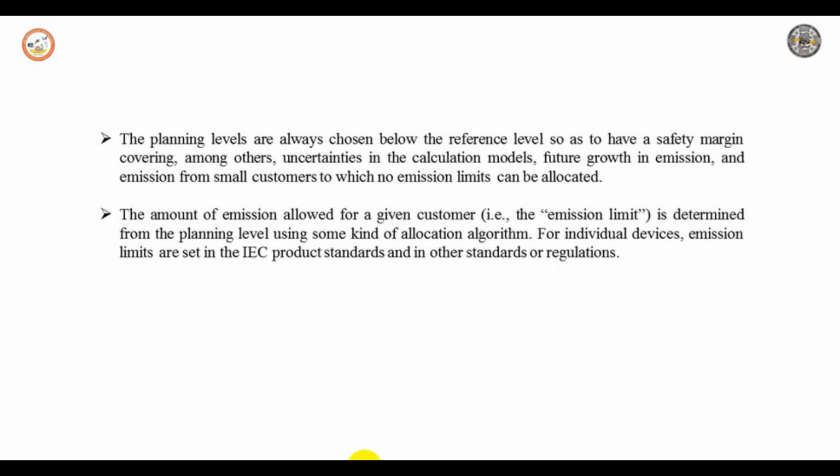The next step to consider is related to an increase in the reference level. This is more difficult because it probably requires changes in international standards on electromagnetic compatibility and also in voltage characteristics. There has been strong objection to this from many sides. Allowing the reference level to be raised when the actual disturbance level becomes high would remove any incentive for network operators to improve their networks. The various power quality and EMC standards are coordinated such that a well-designed grid and well-designed customer equipment would, with a high probability, result in electromagnetic compatibility between the equipment and the grid.